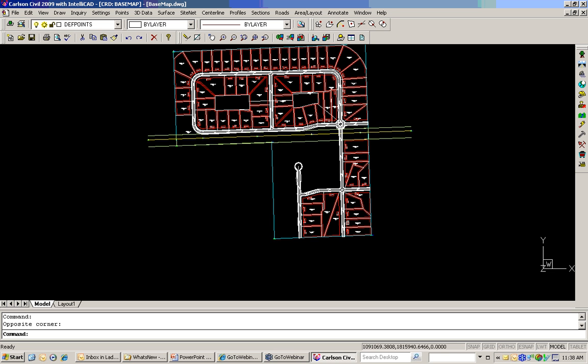Yeah, one way to generate continuous plan and profile sheets up through the roundabout is just to make another center line. That is a center line that would be the center line for your sheets, and you can go through and say, I want my center line to start maybe down here at this part of my site, come up and basically run right through the roundabout and over and around and back over here and even loop all the way out. So that alignment or center line could be used as the formation for all the sheets, and then you would get very continuous looking sheets throughout there.